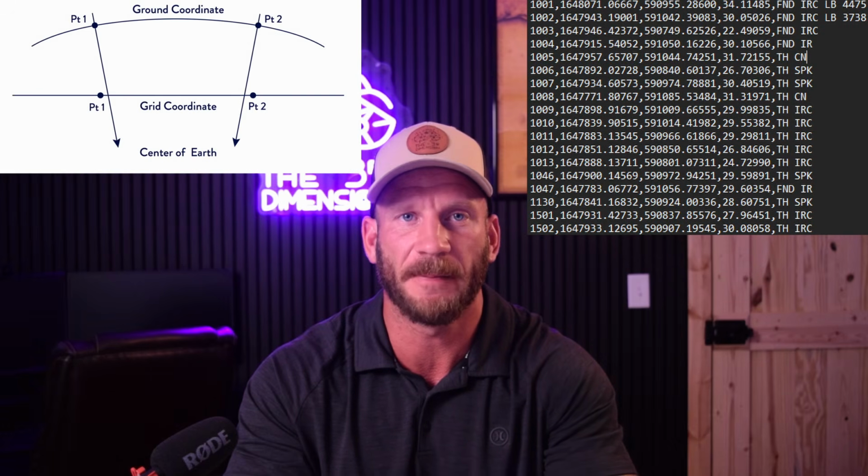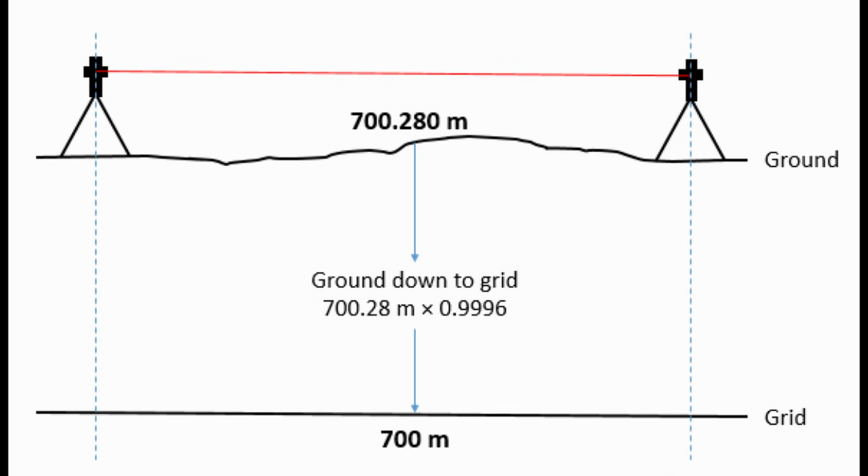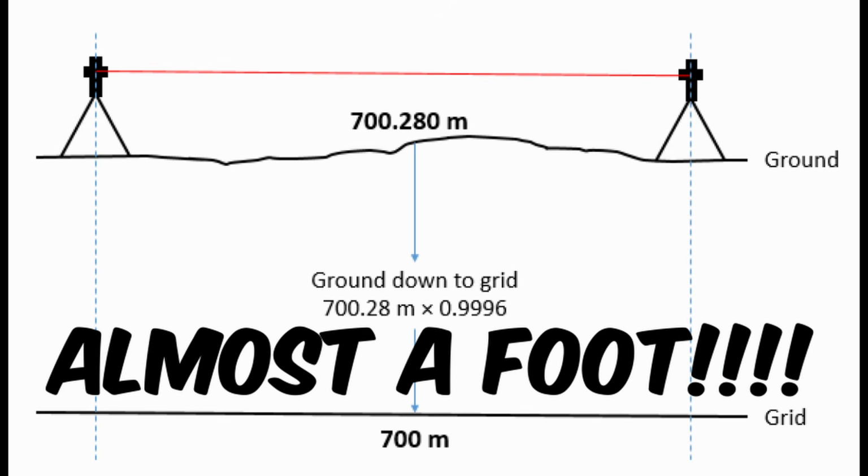Are these grid or ground coordinates? This is a sentence I've probably said 1,000 times in my career. I'm essentially asking if the set of point coordinates I've been handed are in a known grid mapping projection. Why do I care? I care because if I don't know and assume incorrectly, I could be unknowingly adding in a massive source of systematic error.